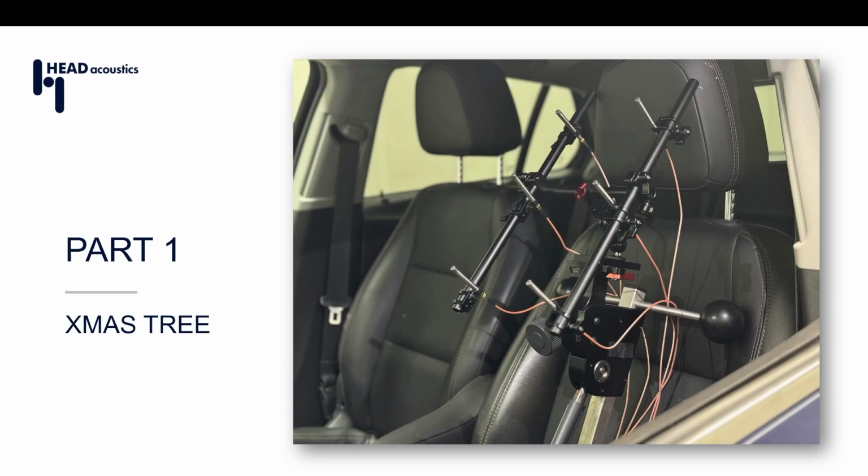Measurements must be conducted in the driver's seat with a recommendation to also measure the other seating positions. And generally, we'll want to conduct our measurements with all sound system user controls like faders, equalizers, etc., set to default.